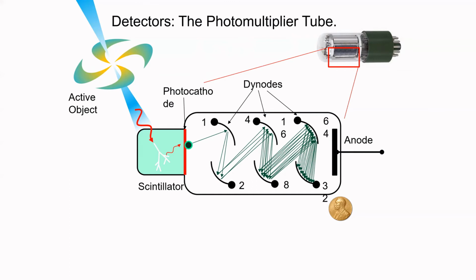The disadvantage with it is that it tends not to be sensitive to the frequency of the incident light, because as long as you go over the threshold to cause a scintillator to scintillate, then after that you're going to get a big pulse of current. And of course there's also then a certain amount of reset time as well. But within those limits, they make very good single photon detectors.